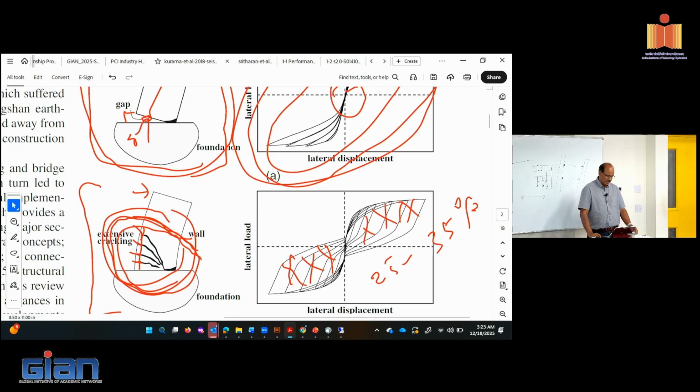But the disadvantage is that because this is a localized large gap, if I put in a rebar here, you will have large strain concentration at that location. So your bar will fracture faster than in a cast-in-place situation. So we overcome that by debonding the rebar locally. Debonding rebar is not difficult. You can put like a duct tape around it or grease it. There's a number of ways you can do it.